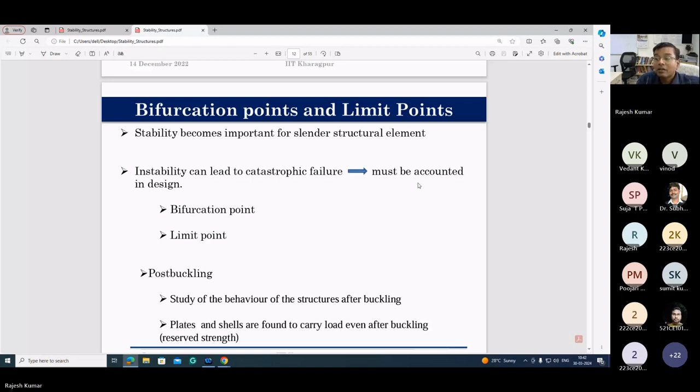For the same strength, I can reduce the thickness. Once you reduce the thickness to save material, it also becomes lighter in weight, increasing fuel efficiency. Then the thickness becomes smaller relative to the a by h ratio.